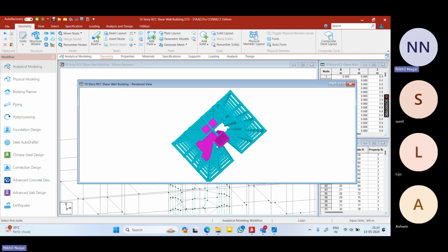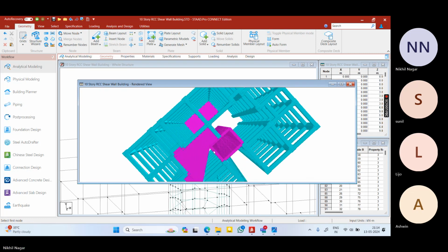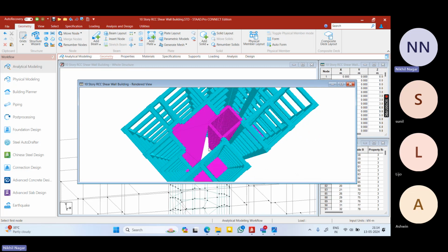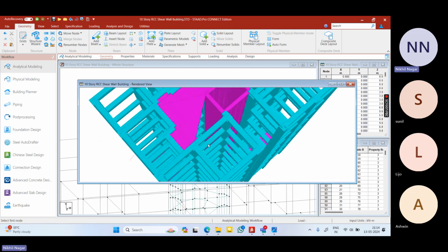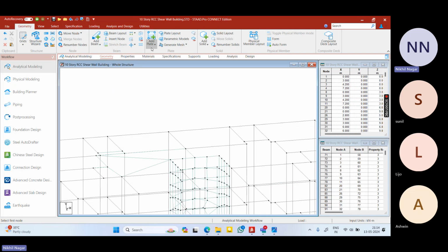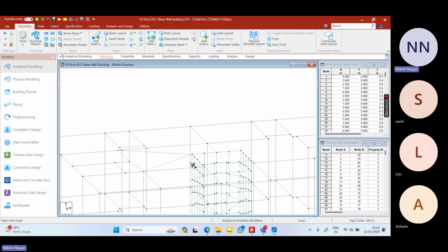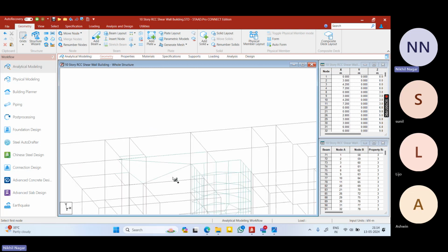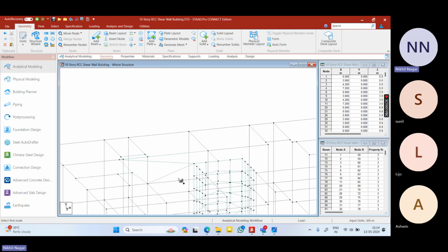So we have made this type of plates region. Now this part is remaining. So this is our triangular plate. The triangular plate option is also available here, by clicking on the down arrow in the plate section. So click on right triangular plate and make the triangular plate.